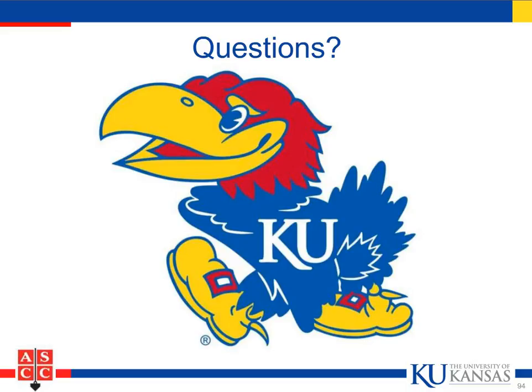Okay, good question, Denise. There's a couple of things here. First, whatever procedure you use, whether you're using blankets or burlap, and I can't emphasize this too much, it's got to be fully saturated when it goes down. I know there are some applications for both burlap and blankets. People think that the bleed water on top is going to wet it. It's not. If you put anything down dry, it's going to suck the water right out. And I'm sure you try to tell all your customers to make sure that it's fully saturated.